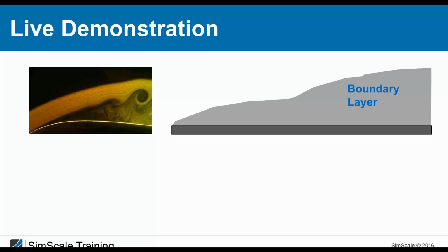And therefore, let's take a step back. Let's think about our wing. If this airstream is flowing around the wing, we might think that air is like a completely inviscid fluid and we will have no friction. But that's basically not true. If you take a deeper look at the very, very thin layer between the air and the physical wall of your wing, you will see that there is a kind of velocity profile, which means on the wall itself, the velocity is zero. There the air is sticking to the wall. And if you go far away from the wall, you have the free stream velocity.